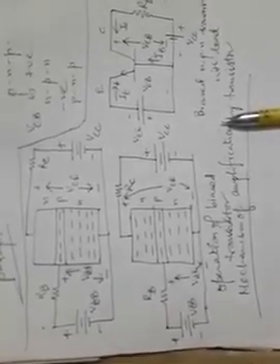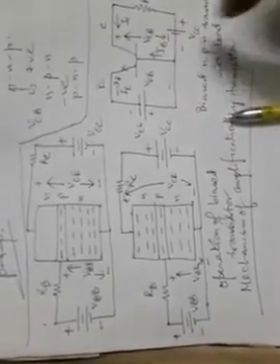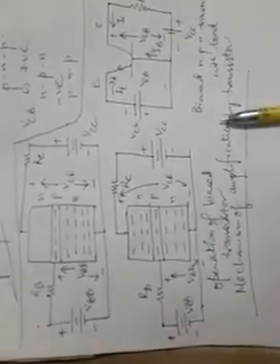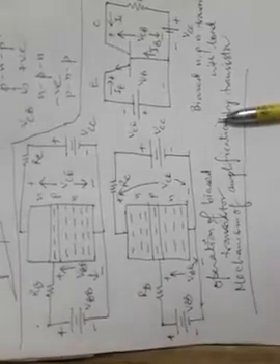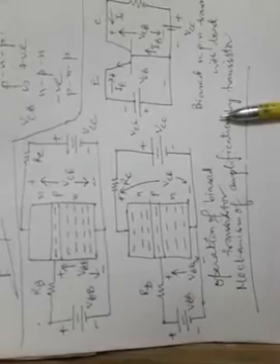So this circuit shows the normal way of biasing, and the reference current and voltage directions and polarities are respectively shown in this diagram. So let us come back to these two diagrams to see how the operation of the bipolar transistor is happening for amplification of signals. Now in this case, one thing has been assumed: that the resistances of the bulk of the emitter, base and collector regions are negligible and the applied voltages appear entirely across the junctions.